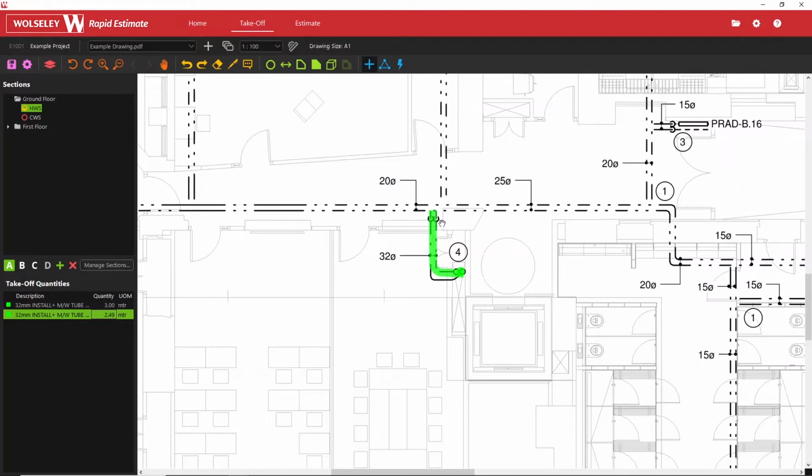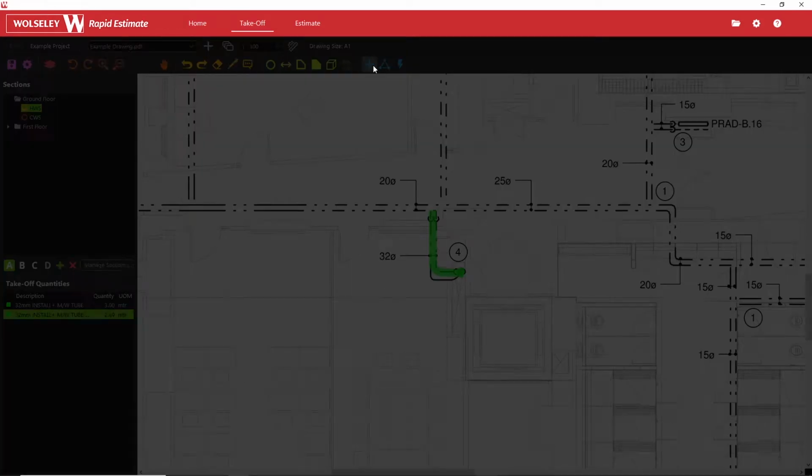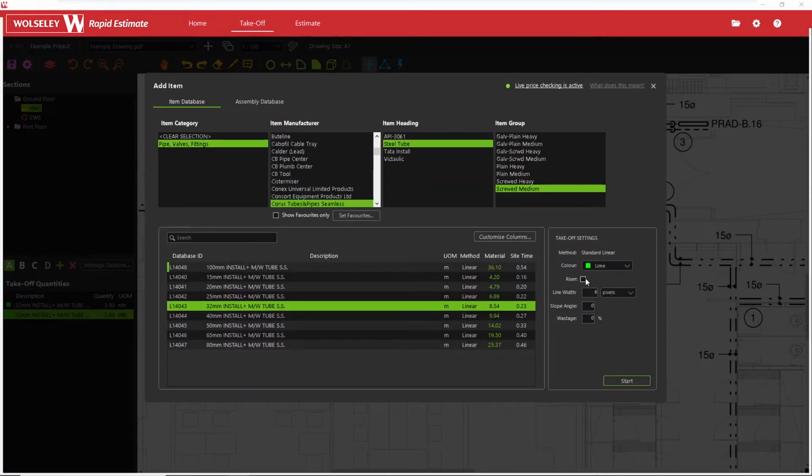Once again, if I needed to actually do another riser count to allow for that set piece, I could just press my plus icon, click the fact that I would like a riser, adjust it down from 3 meters to whatever you believe would be suitable, and then just do another stamp. Okay, so that's absolutely brilliant.